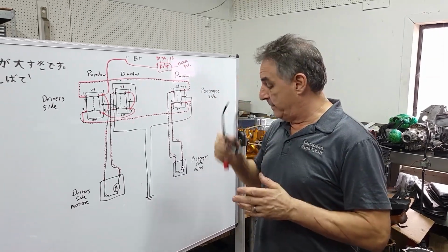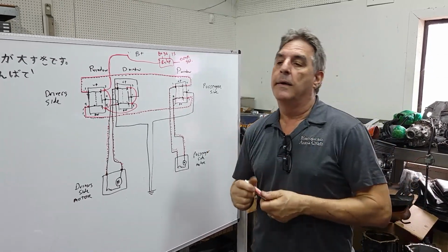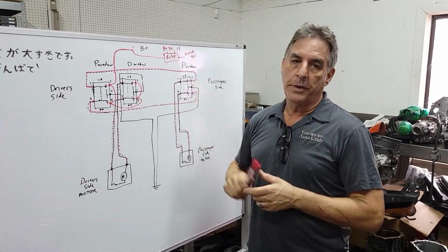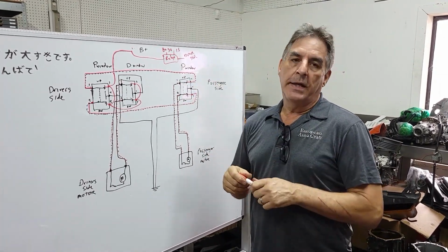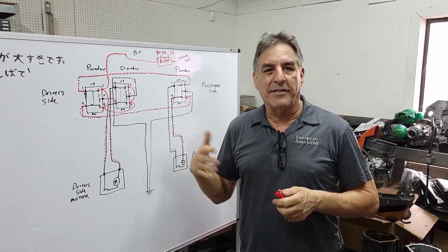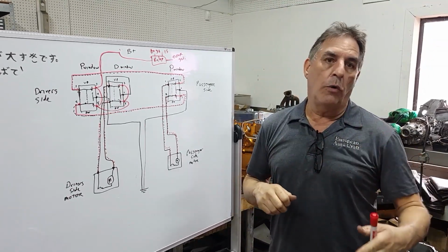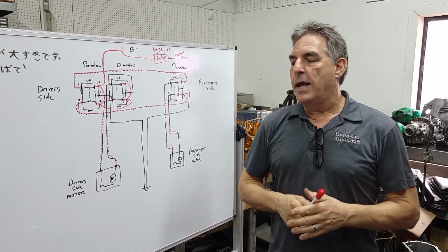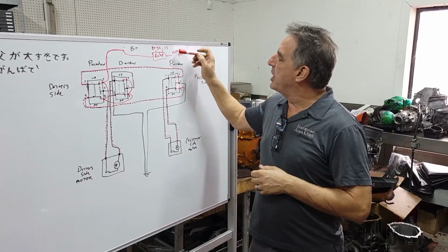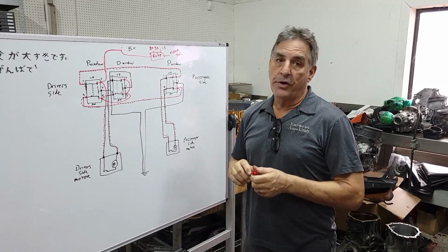Now, sometimes your battery goes dead mysteriously. You don't know why. A lot of times it's not the relay's fault, but it's the door pin switch. This relay never shuts off. So if you're having trouble with your battery dying, or the car cranks a little bit weaker in the morning, just check to see if with the key out and the door open, your windows still work. If they do, they're not supposed to. That means this door pin switch hasn't sent the signal to the relay to turn it off. That's a very common problem.